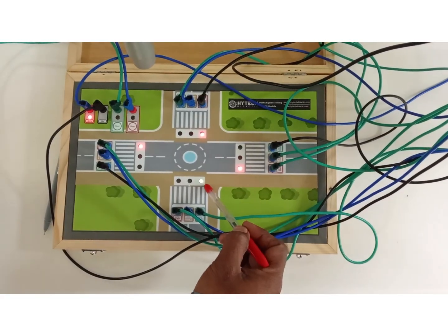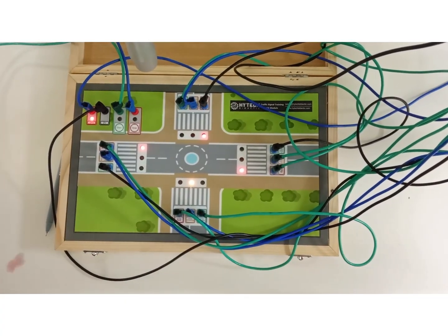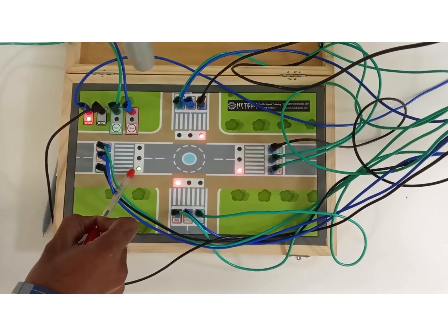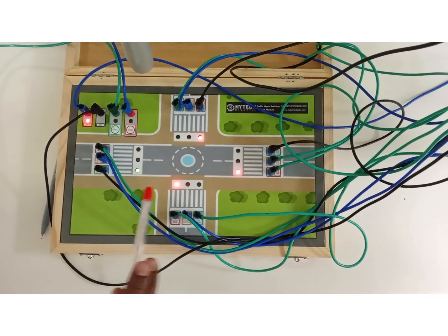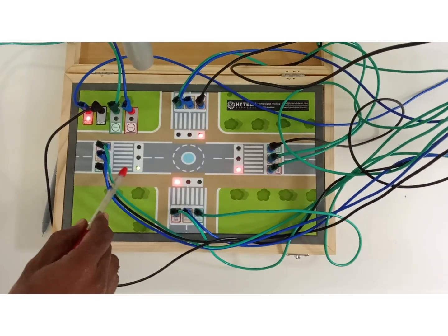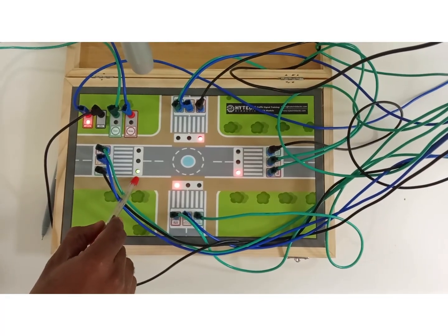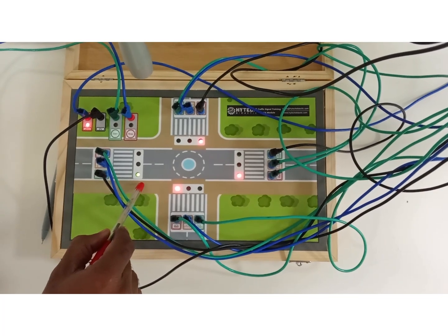After these 25 seconds it will shift to yellow for 5 seconds, then to red. Then green is on for the fourth route, but routes 1, 2 and 3 are in red. There is no movement of vehicles there, it is red. The fourth route's green stays for 25 seconds, and the timer counts from 90 to 115 seconds.